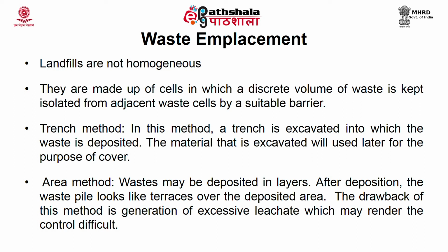But the disadvantage of this method is that it leads to excessive generation of leachate, and it is very difficult to have proper control over the area method, because once you start loading one layer, by the time you come back to the same place, almost the degradation would have occurred.